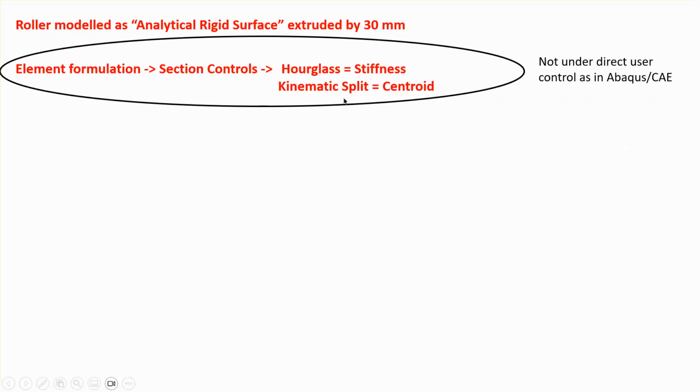So let me just quickly mention the formulation that the YouTube reference is using. This kind of thing is not accessible directly to the user. Now, it is obviously possible to create an INP file with 3D Experience and then go and include anything that is not put at the direct discretion of the user, but that's not what I'm doing. So, the mass scaling factor that this YouTuber is suggesting is 2,758 and factor of that.